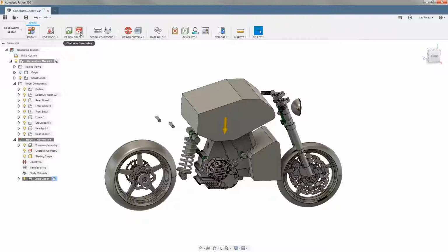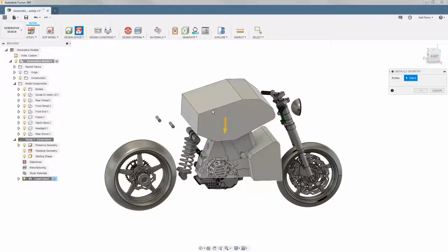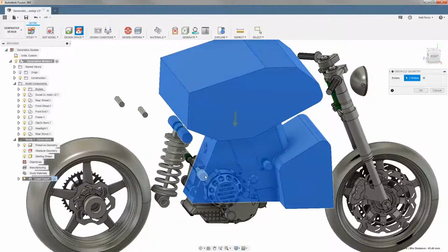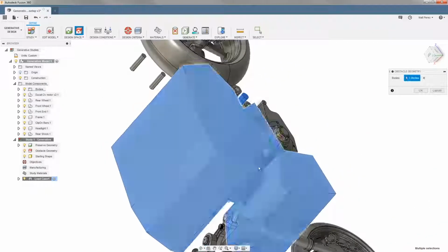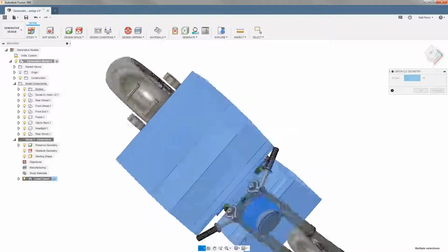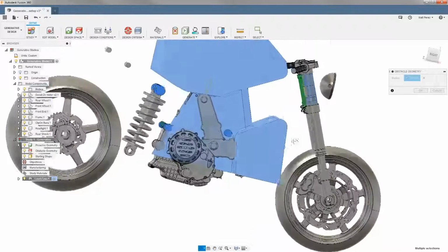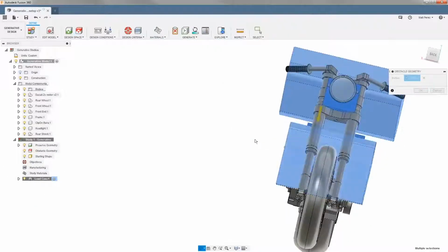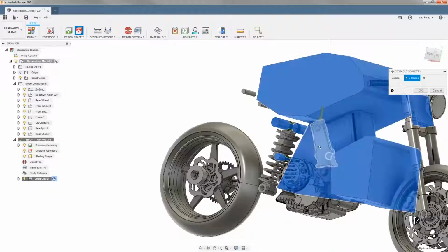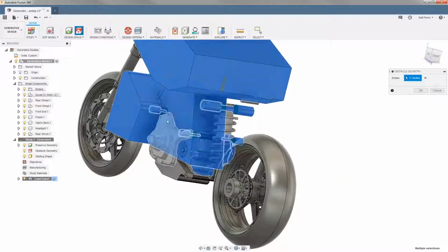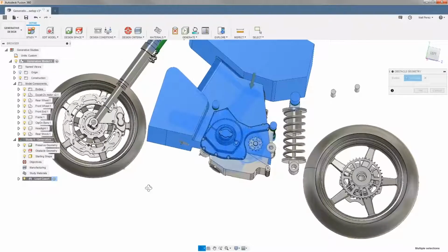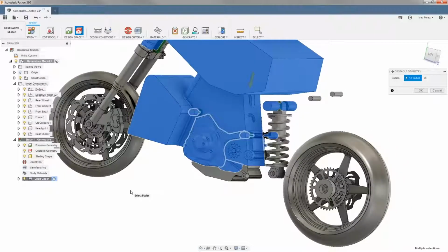Now that we have all these created, we can go into our obstacle geometry and start selecting all the things that we created as obstacles. So these are going to be areas around the stem that we created, areas on the outside of the mounting points for hardware. And because we have additional geometry that is outside of our model, such as these timing covers, part of the engine case and the clutch cover, as well as on the left-hand side, this engine case here, we want to make sure that we select those, or that we go back into our sketches and create primitive versions of those.